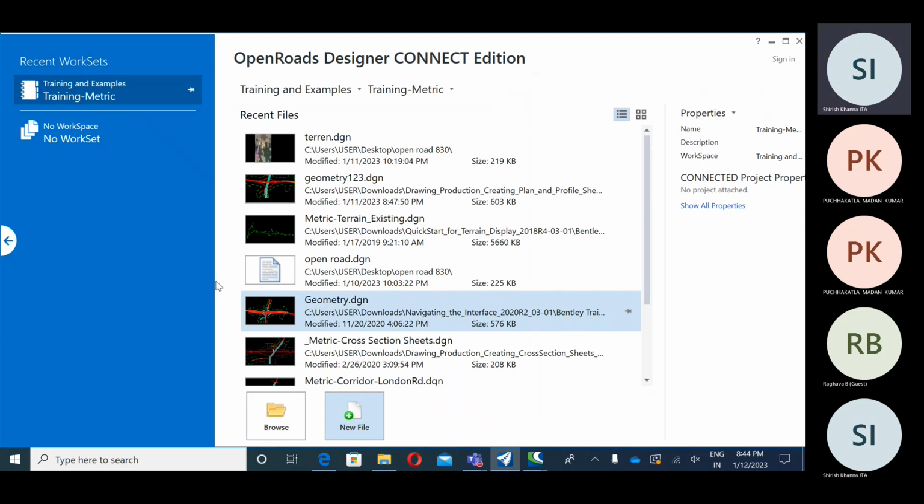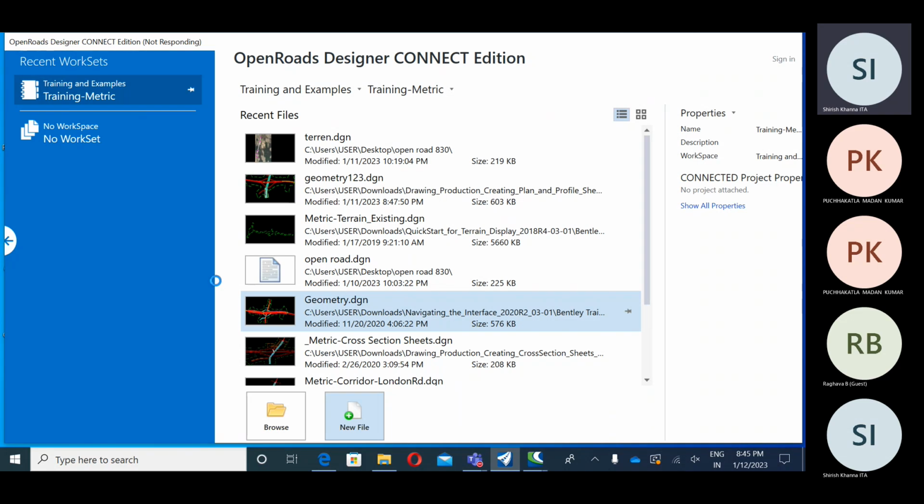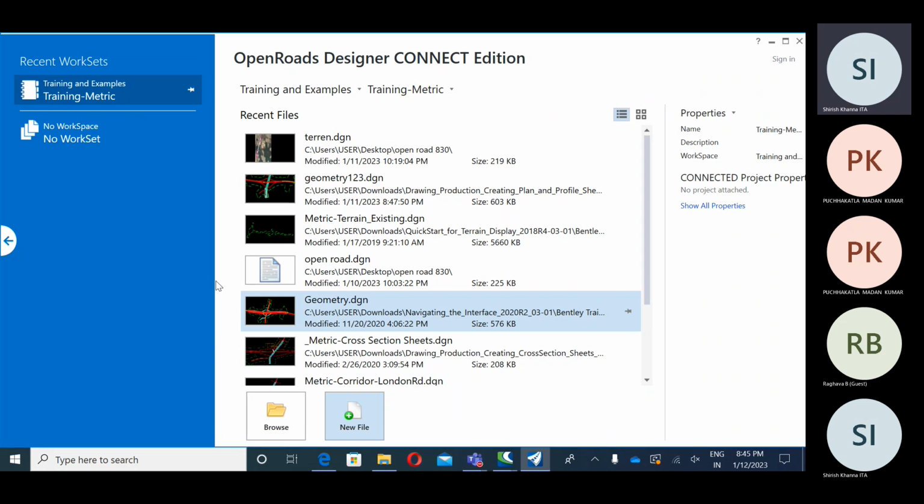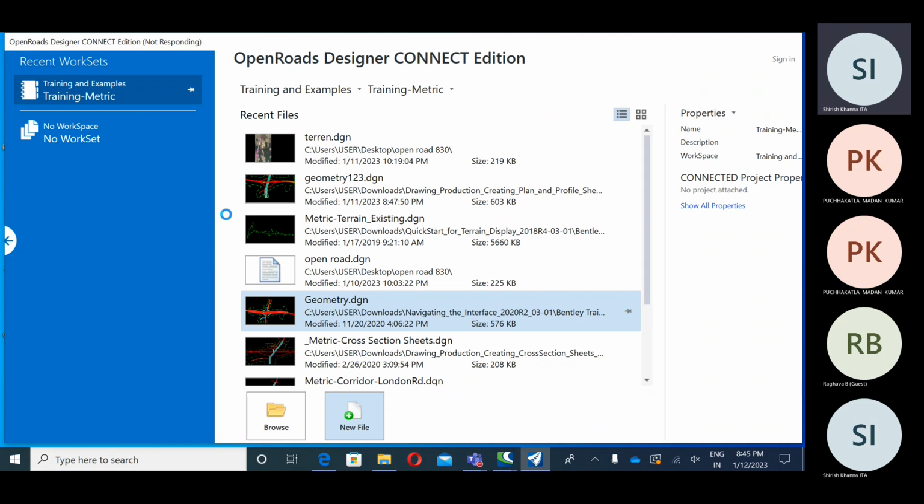Now we have to attach that file, named aerial topo, in which we have some points. We have to create an alignment first, as we did yesterday in the lab. Same thing again, and then we are going to give the start stations, end stations, annotations, and then apply the horizontal alignment report, and then go for the vertical alignment. This is our today's task.